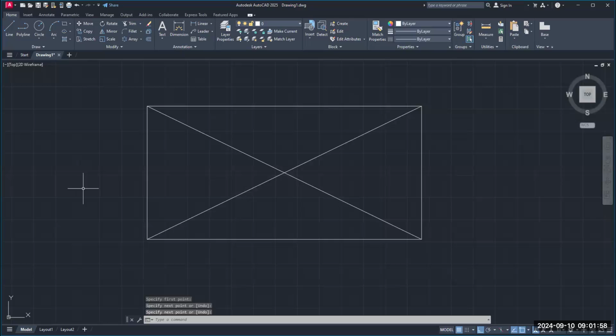Now, watch this. If I want to draw a line from the midpoint, now, it's not snapping to the midpoint. All right, this is very important. You got to watch very carefully what I'm getting ready to do and do the same thing. I want my cursor to snap to the midpoint, but it won't do it. It's only snapping to the endpoints. It's not snapping to midpoint. Mr. Morris, how do I fix that? Type in this word. Type in O snap. O snap.